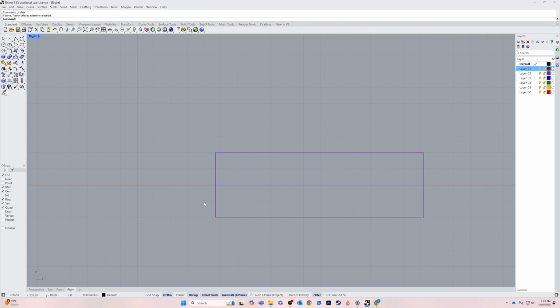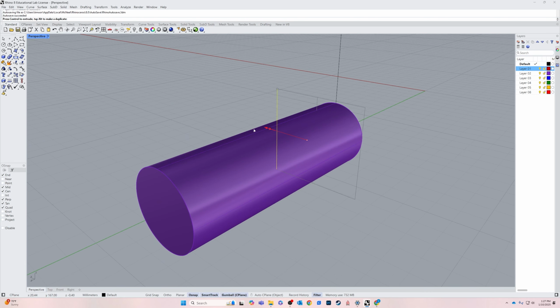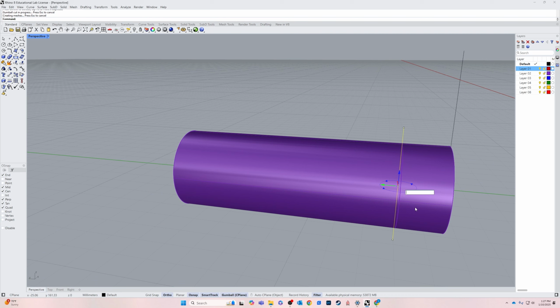I'm going to draw a line from this end here straight up, and offset 20. Select this object, go there, draw it down, square it out, go to perspective, and hold down shift and use our cutting line to cut that section into a separate one. Okay. Delete.